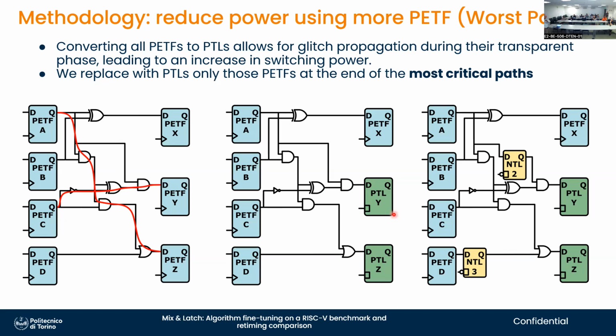If the circuit has been optimized to be redundant, then there is always a place to insert those slowdown buffers or latches. You need the redundancy because you need to have essentially each. By the way, we may need to insert these delays also on gate inputs, not just gate outputs. That might help. Okay, so in the wire that is the AND. Yeah, exactly. So we don't slow down each gate. We can slow down also the input. Without that, we would not be able to achieve these results.